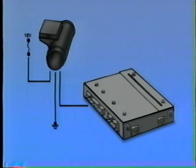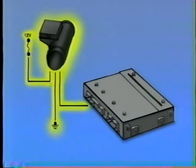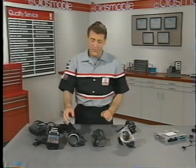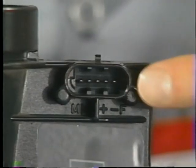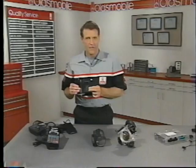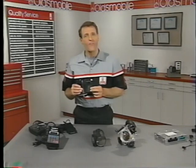The basic circuit for a MAF sensor looks like this. The sensor has 3 wires: power, ground, and a signal output to the ECM or PCM. If you see a MAF sensor with a 5-wire harness, that's a combination device with a manifold air temperature sensor built in. The MAF sensor still uses 3 wires. The remaining 2 are for the manifold air temperature sensor.